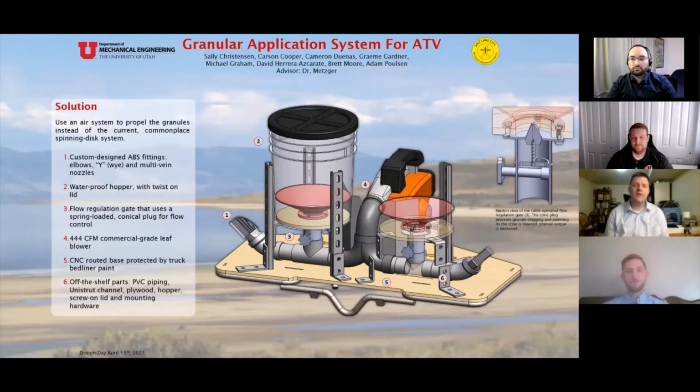A custom-built valve is used to precisely meter the pesticide. The image on the right shows the internal view of the valve, which represented numerous engineering challenges. The valve is cable actuated by an index turn handle, which moves a cone up and down to increase and decrease the rate of pesticide flow. It's spring-loaded to the closed position, preventing pesticide spills in the event the valve is damaged.